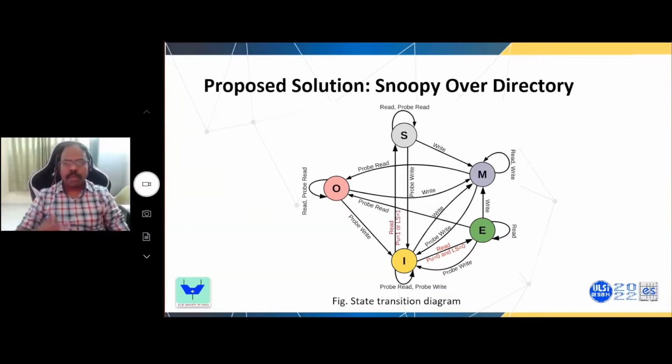This is how the protocol is implemented, and the only additional updates required are when a cached block is present across multiple chiplets. Since the emerging link acts as a broadcast bus-like architecture, the order in which the requests are made is also the order in which the coherence requests are serviced, thereby maintaining event ordering within the protocol without any additional requirements. The implementation of the protocol does not depend on the protocol within the chiplet, or the communication implementation like the frequency of communication within each chiplet, thereby providing a very flexible and modular protocol implementation.